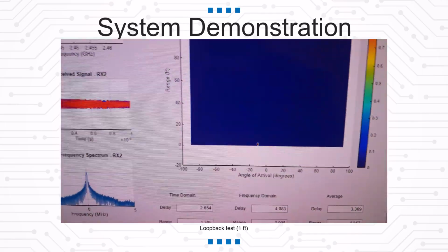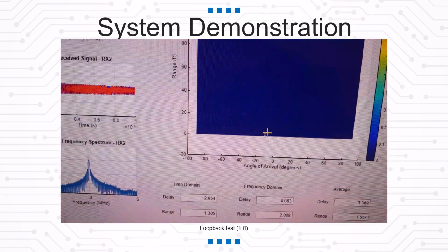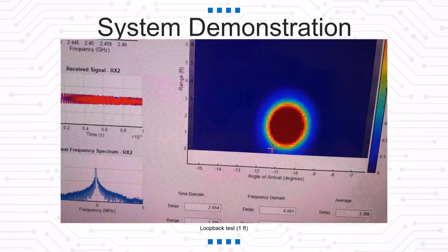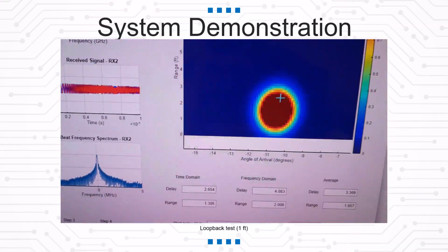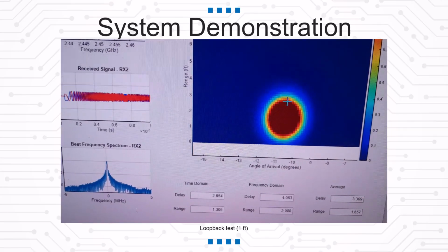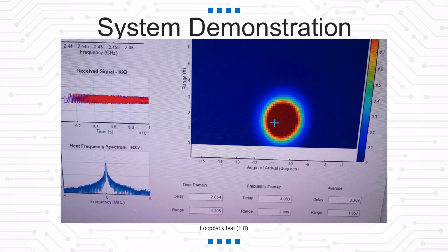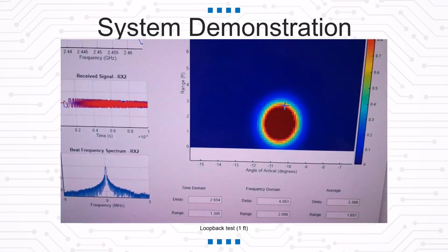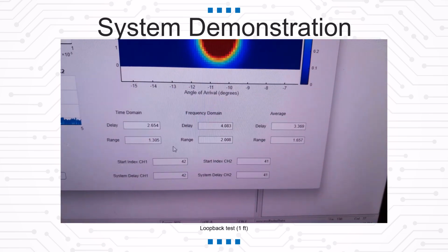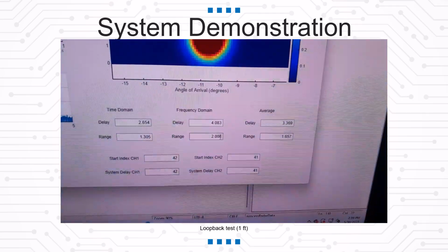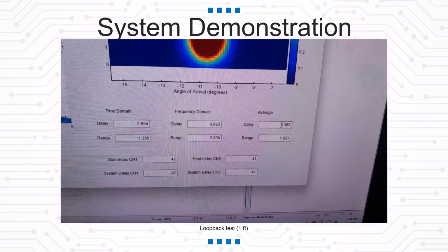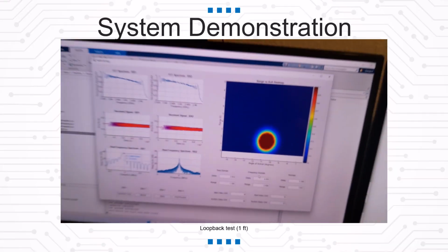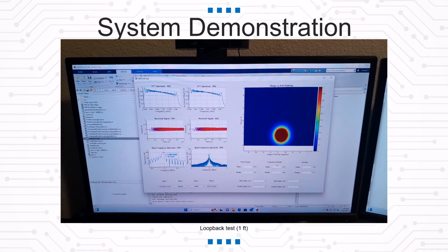And the plot, you can see it's right here, and I'll zoom in on it. There are actually 3 samples here: the time domain, the frequency domain, and the average of the two, and that's why it's kind of spread out. So not completely identical results, but we are literally trying to measure 1 nanosecond.